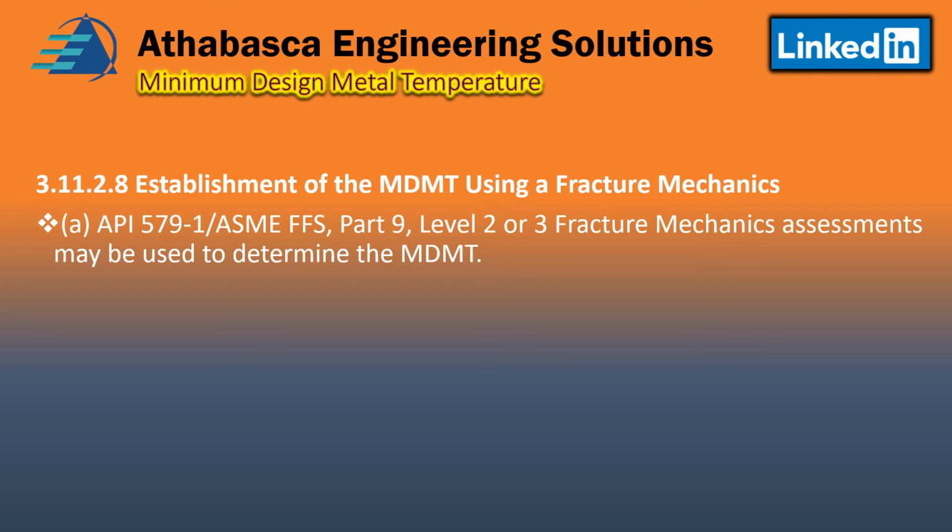And basically, they require a Part 2 or Part 3 fracture mechanics assessment, and that can be used to determine the MDMT. So in this case, you're basically using inspection data, and you're looking for flaws, and you're determining, based upon the flaws, what your MDMT is capable of.